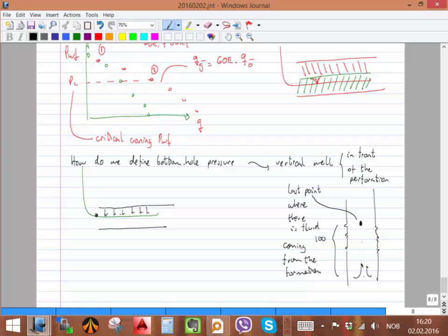When you have multilaterals, for example, you know that you have some wells that have 1 or 2 or 3 laterals. So how do we deal with that case? We can make a compound IPR. We can say that the PWF is here and calculate an equivalent for all of these layers. But we can also define for each one of them a PWF1, PWF2, PWF3, and then calculate IPR or test IPR for all of them. We will see maybe later when we talk about networks. I prefer to just leave that for networks.